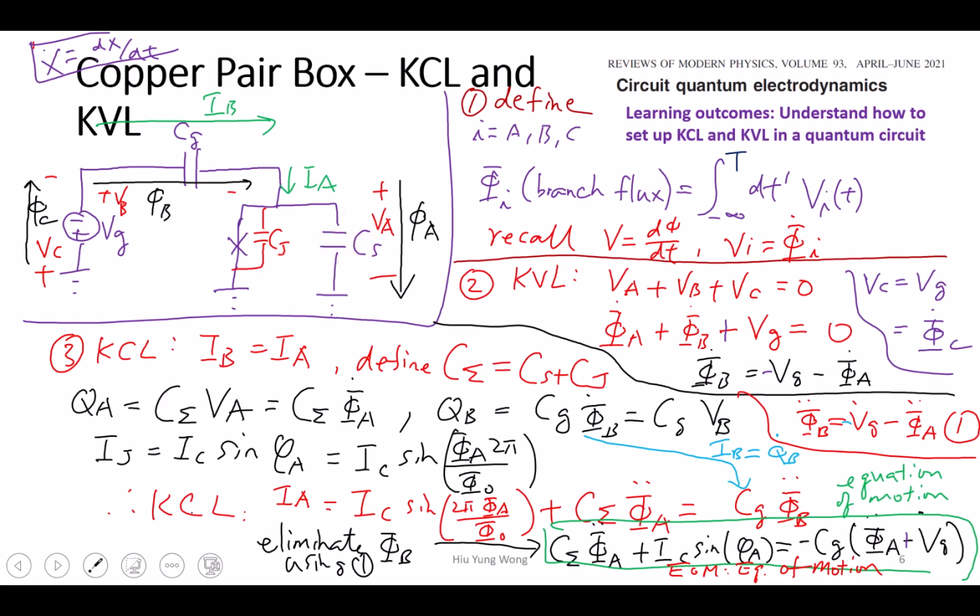By the way, sometimes people try to test the superconducting Josephson junction at room temperature to do the screening, because cooling time to dilution refrigerator temperature is very time consuming. And how do they screen? They find a correlation between the quality of the Josephson junction and its leakage current at room temperature, which is just a capacitor leakage current, right?